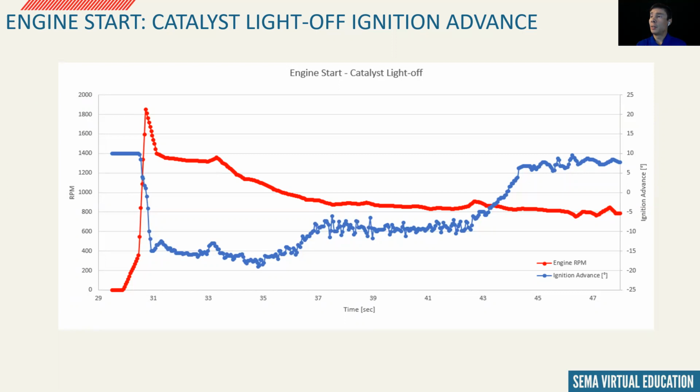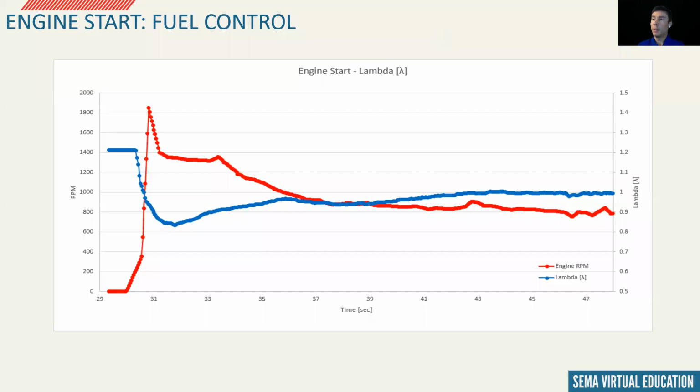If we have an application where we have affected the relationship of desired and actual load, we might need to rectify errors before catalyst light off works as intended. Like we mentioned before, during a cold start, our tailpipe emissions will equal the engine out emissions because the catalyst temp has not reached the 250 C target to start reducing our emissions. Because of this, we need to have good fuel control. Also, we will have closed loop fuel control. We will not have good closed loop fuel control to help us for at least 7 to 10 seconds after the engine start.